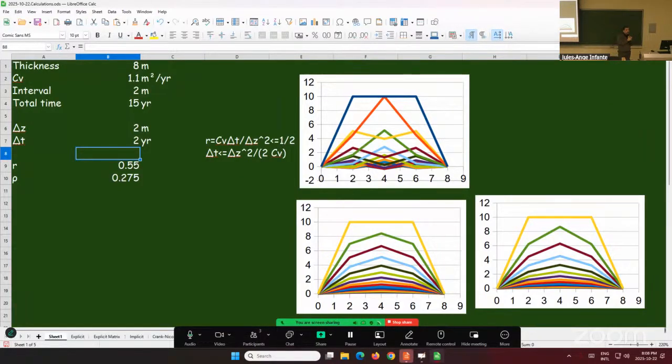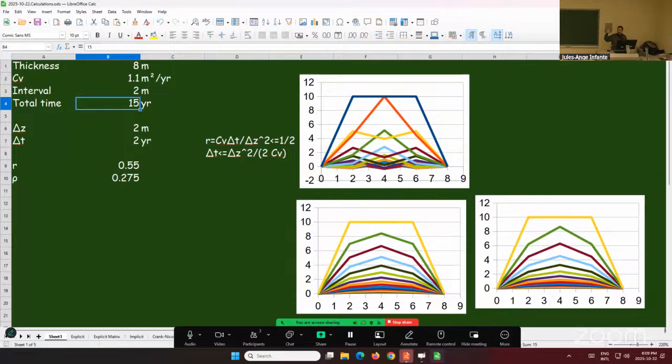You can make that time step bigger, as we've seen, right? And it will give a reasonable result, but there is a limit. And it will never be obvious what that limit is, unfortunately, before the numbers don't make sense anymore. So keep that in mind and think about the explicit method criteria as a general guide as to what will make sense.